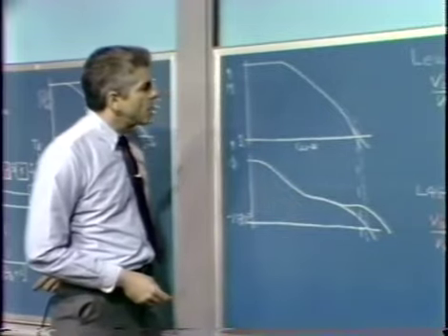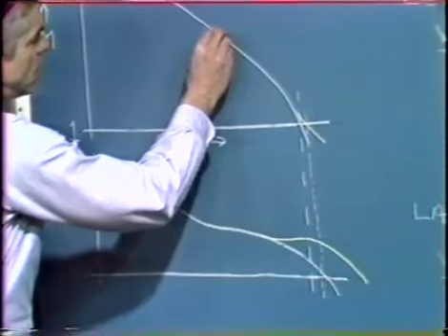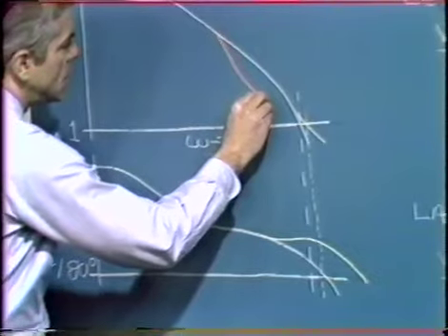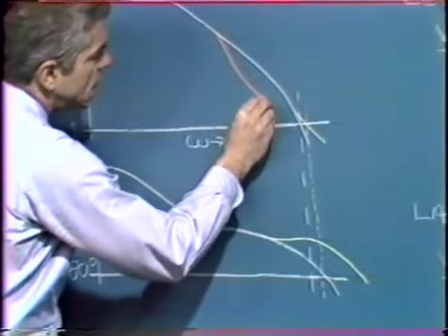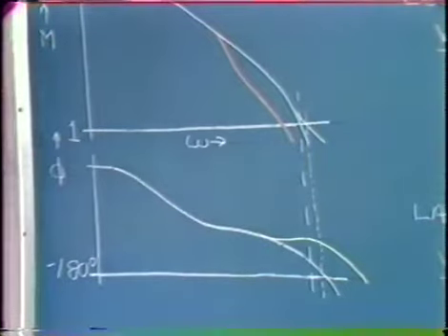So the modification that we might make in the case of lag is to possibly put the pole in here. The curve would drop down. We then add the 0, and we eventually end up with our compensated curve going parallel to the original curve.